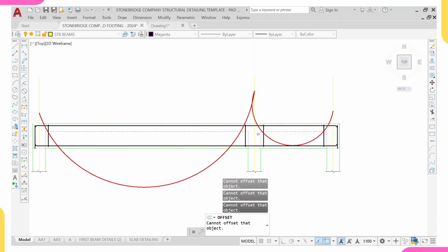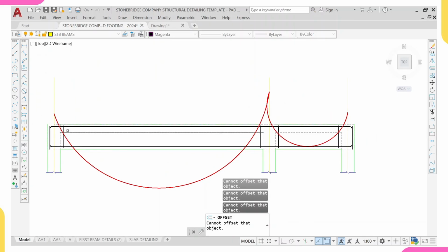Then coming over to this support, which is this beam, and also this is a beam. We're having moment at the top, so we must counter for that moment. If not, there will be a failure. So to counter for that moment, we'll provide reinforcement at the top, and also provide reinforcement at the top.